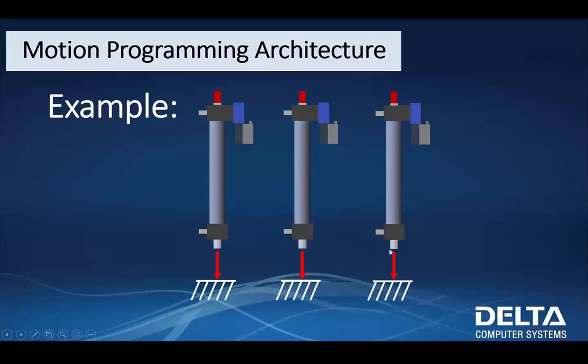This machine is flexible enough to do both of those. And we do actually have a customer who's done a very similar application like this in real life. Made a real good use of the machine, being able to do long parts, but then high productivity for the small parts. So occasionally we want these cylinders to move independently, do a pressing operation where it closes the press, builds pressure, dwells a little bit, and then decompresses and then moves back. A very classic press cycle. And we want them to do it independently and then sometimes together.